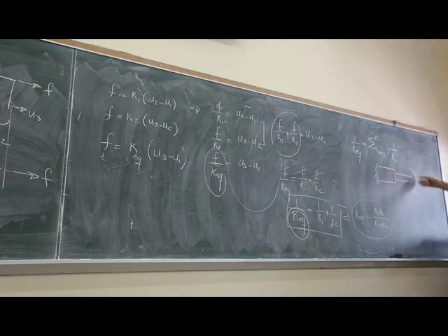Since these experience the same moment, or torque or torsional deformation, they are said to be in series. But physically, as I also introduce the concept of parallel, series does not necessarily mean that they have to be physically connected like that. They can have different geometric configurations, as long as they experience the same force.